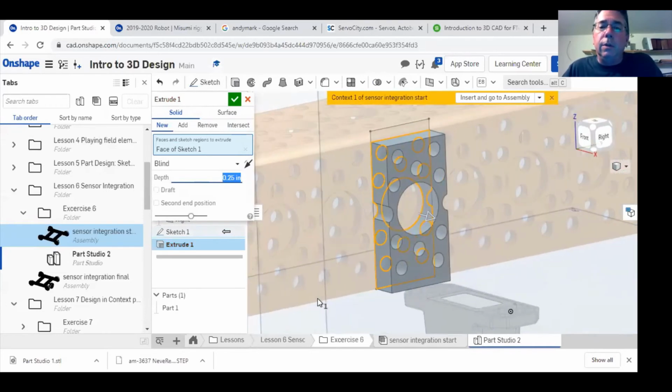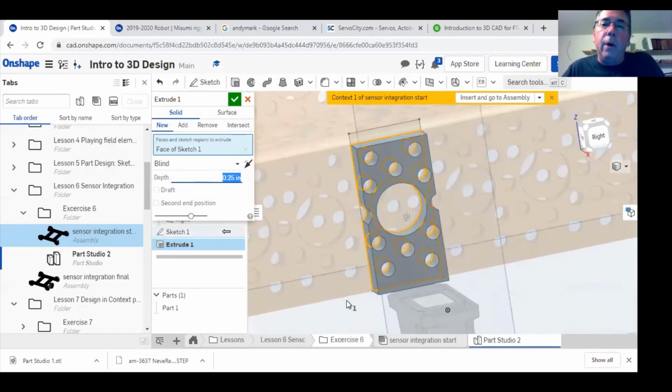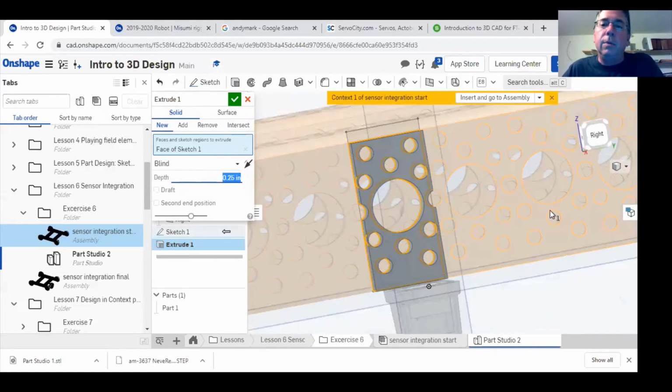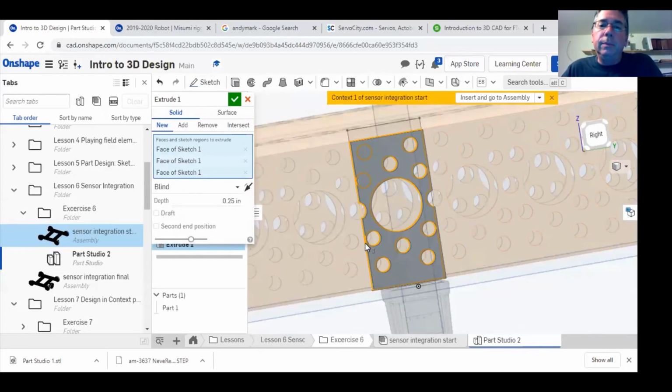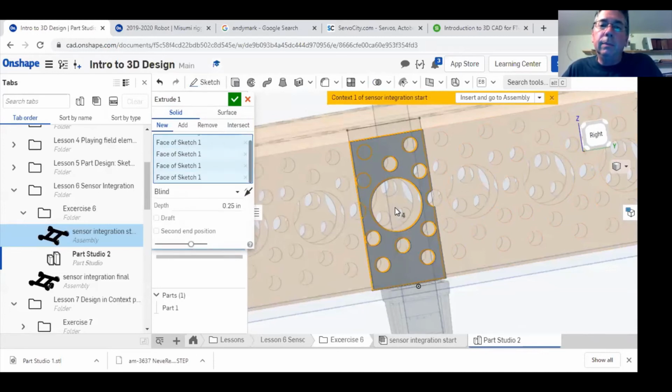And notice that it looks like Swiss cheese. It's picking up all the mounting holes of that C channel. So if we go in here and we fill them in by just clicking on them, those will be the 2 mounting holes that we use for our fasteners.